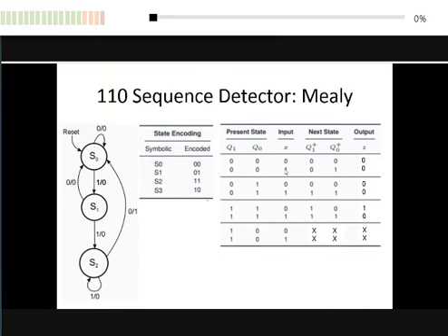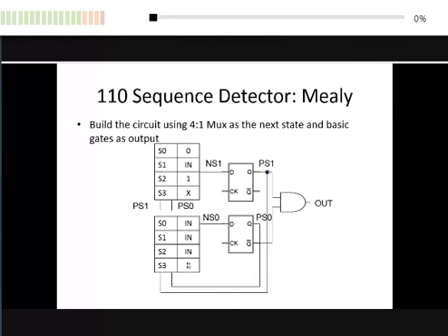So you will label as in. When present state is 0, 1, Q0 plus also follow in. When present state is 1, 1, Q0 plus also follow in. So that's why I label all of them as in. And S3 is don't care lah because we don't use it. So there goes your multiplexer. Very easy. Alright.